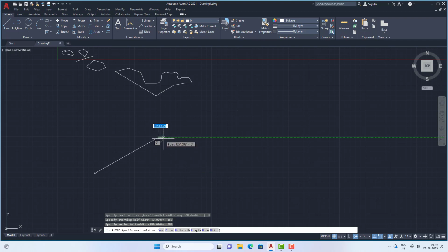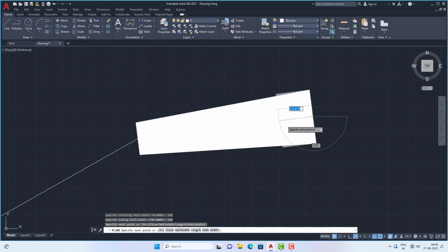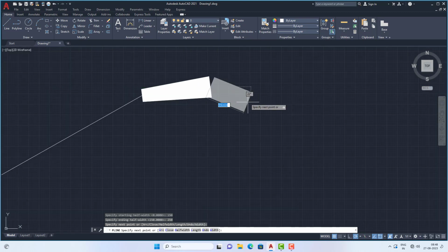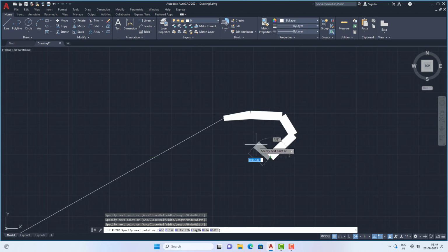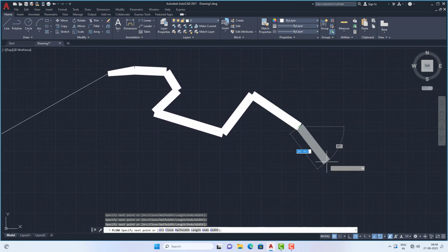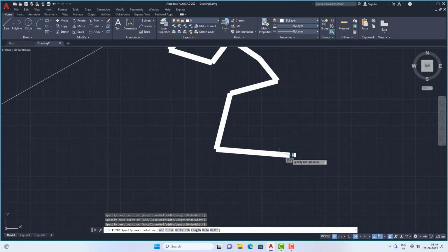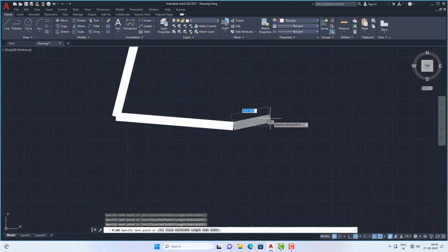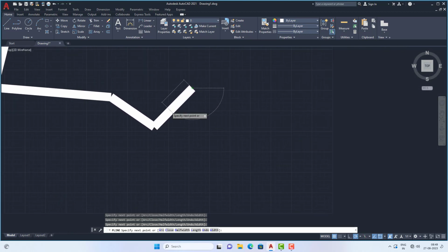See what happens here, I am zooming. See, this is the starting width and this is the ending width. A trapezium like this is created. And at the end, whatever the value of the end width is, the line will continue with the end width value. See here. So like that, you can set how much width or thickness you need the line with. You can activate that option.